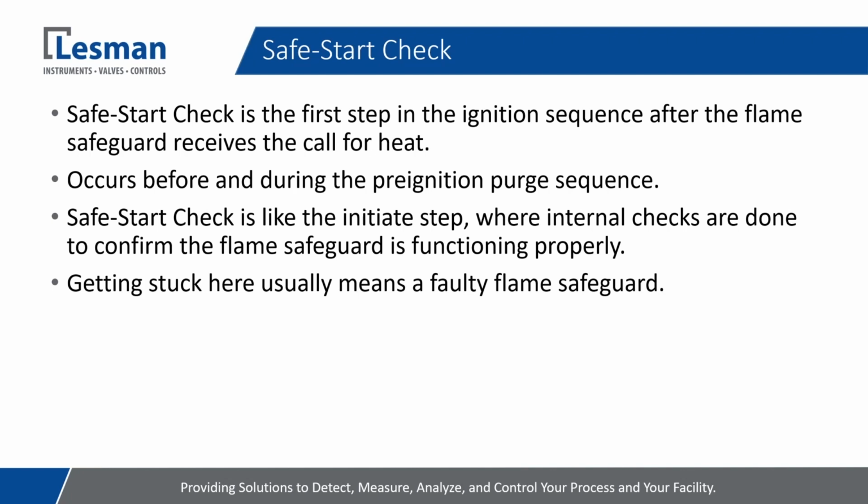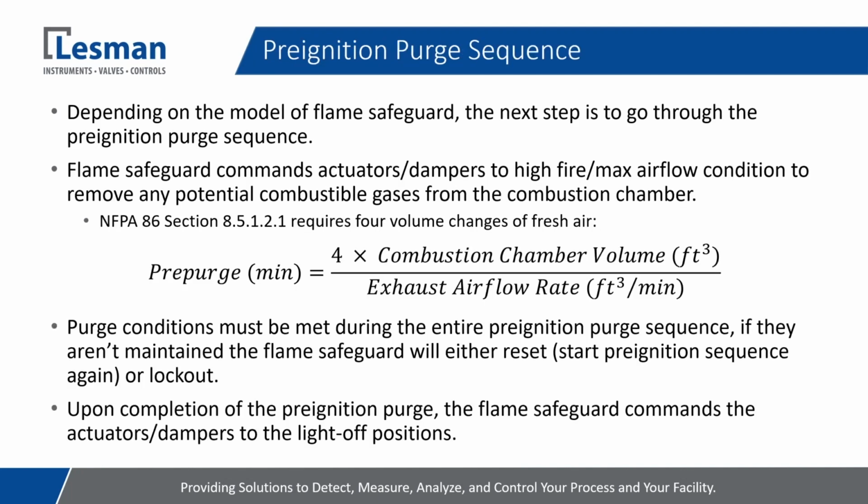I haven't ever come across an application where the system gets stuck in safe start check, but looking through the literature, it sounds like really the main thing is that if it's not completing the safe start check, there's some faulty component in your system, whether it's the flame safeguard itself or the amplifier card or the detection device. So now that we are going through the safe start check and have gotten the call for heat, we now go through the pre-ignition purge sequence.